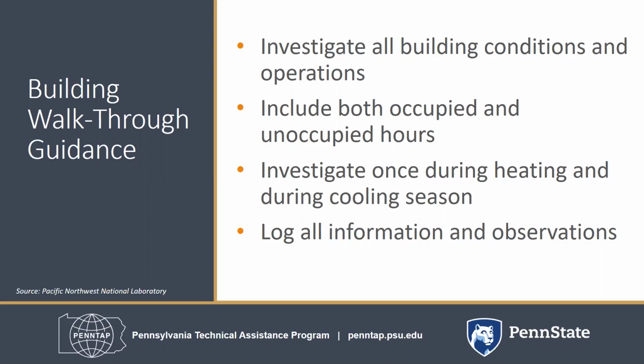Those times when the space is being used during the nights, weekends, or even during holiday breaks. Consider investigating two times a year, once during the heating season and then again during the cooling season. Also consider during shutdown periods, such as a long holiday, equipment maintenance shutdowns, or the summer if you're a school. Remember to log all of your information and observations. This will help capture opportunities and ultimately calculate potential energy savings.